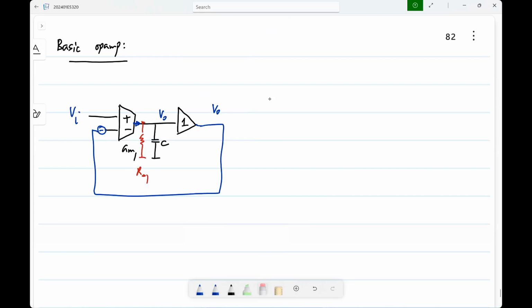So what else can we do to prevent this problem? The main point is, if there is some current coming out of GM1, you will definitely have some difference voltage. In fact, the difference voltage is the cause, the output current of the GM is the effect. If GM has to put out some current, it has to have a difference input voltage. And that's what has to be prevented. What else can we do to prevent that? We had one solution, but we may want more than one. What else is a possibility?